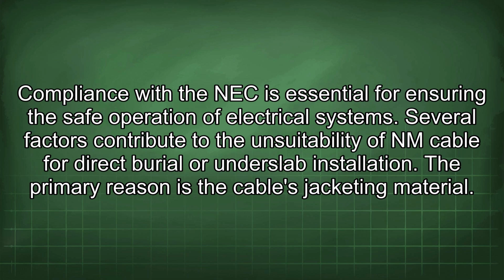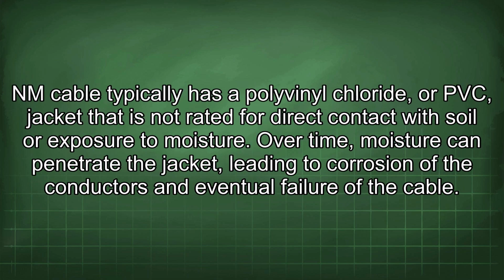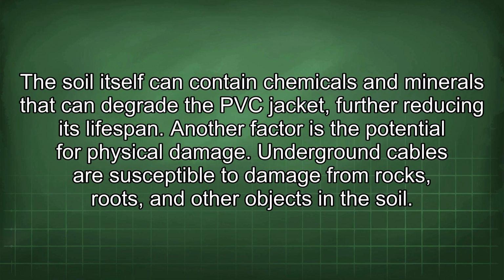The primary reason is the cable's jacketing material. NM cable typically has a polyvinyl chloride, or PVC, jacket that is not rated for direct contact with soil or exposure to moisture. Over time, moisture can penetrate the jacket, leading to corrosion of the conductors and eventual failure of the cable. The soil itself can contain chemicals and minerals that can degrade the PVC jacket, further reducing its lifespan.